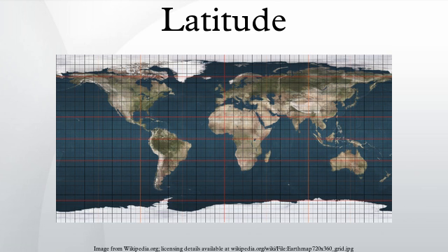For example, the defining values for the WGS84 ellipsoid, used by all GPS devices, are a = 6,378,137.0 m exactly, 1/f = 298.257,223,563 exactly, from which are derived b = 6,356,752.3142 m, e² = 0.006,694,379,990,14.